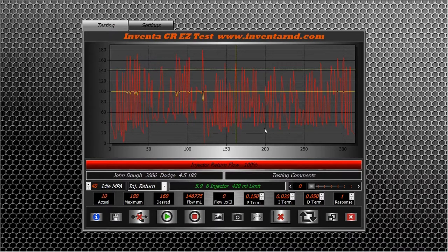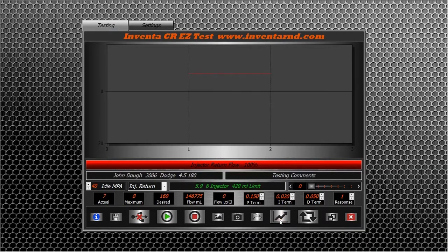A scope is the greatest information that you can have in Common Rail, or any type of testing as far as I'm concerned, to do with mechanical things, with sensors, and you're looking for pressures and pressure over time. A scope's the only way to do it. So we're going to go ahead and clear the scope again and turn it back on.